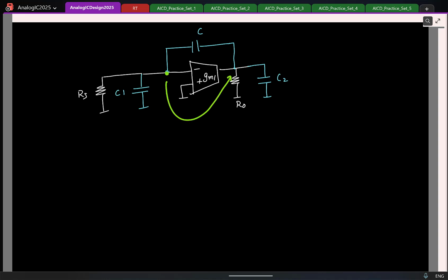node to this node. But being a voltage controlled current source, in this case, at the output side, what quantity is fixed here? The current is fixed. So which means if I ask the transfer function from this voltage to this current, what will be the ratio of this current to this voltage? Sorry? GM or something else? Can you look carefully? I mean, maybe if it's not clear, I'm looking at the current flowing this way. I'm interested in, if I know this voltage, what does this current?